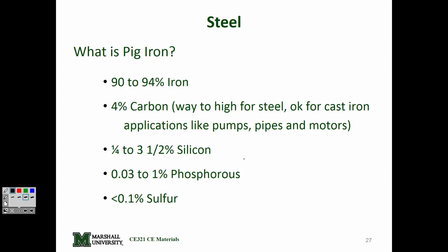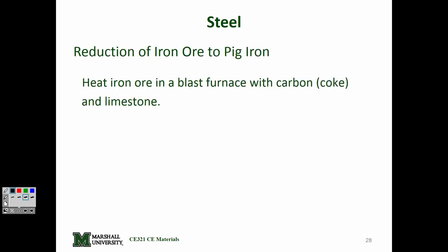That's a cast iron kind of condition. And any of you have had much to do with cast iron, when you hit cast iron with a hammer, it's going to crack, especially if it's hot. So it's very, very brittle, and we don't like that in our steel. And we've got other smaller constituents in there that we'll try to remove as well during our process.